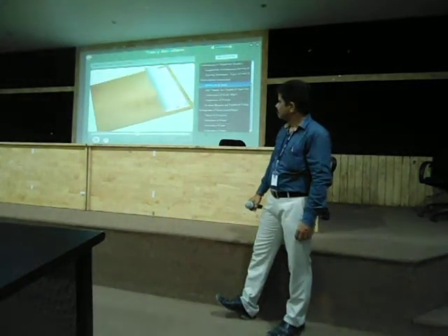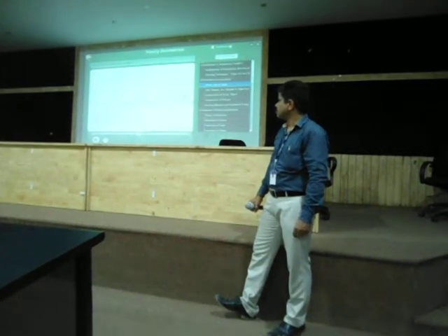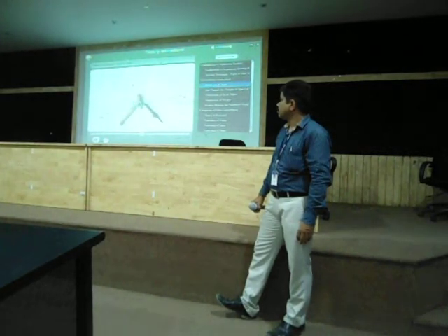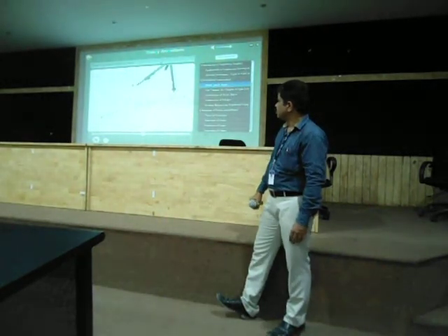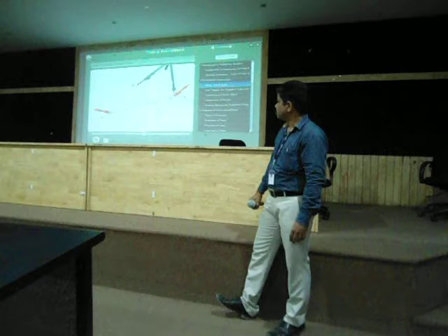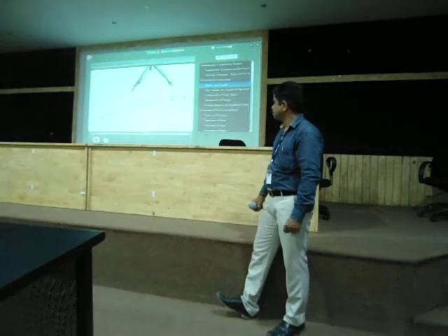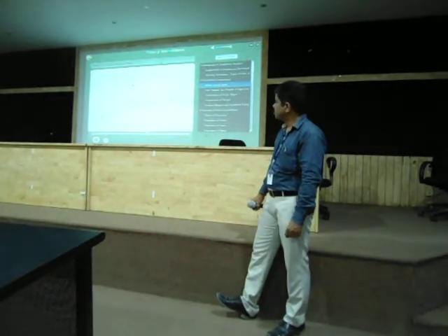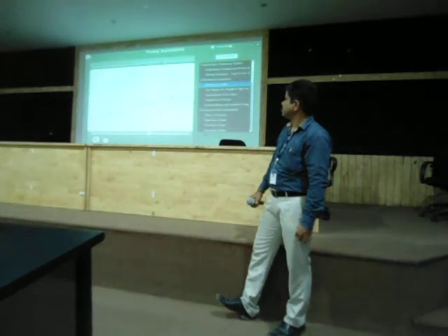Now let's understand how to draw a perpendicular line to another line AB from a given point P which is not on line AB. This is somewhat extra knowledge now. Using a compass, draw an arc of radius, say R1, from point P which cuts the line AB at points X and Y. Now taking X and Y as centers and some radius R2, draw arcs cutting each other at point Q above line AB.